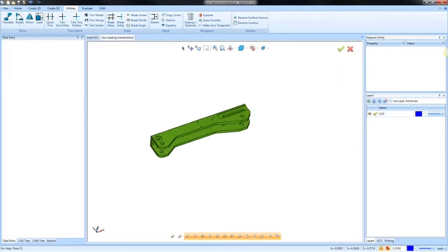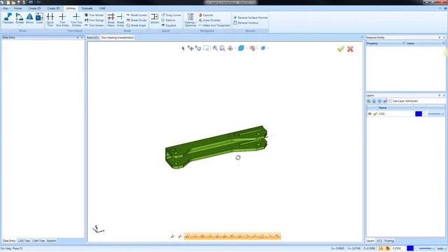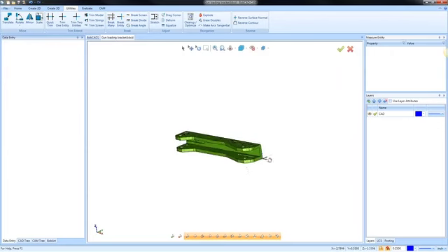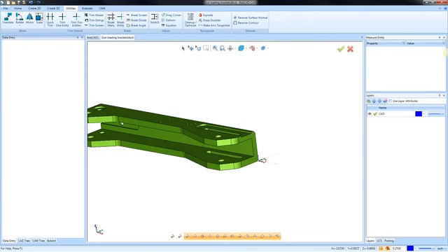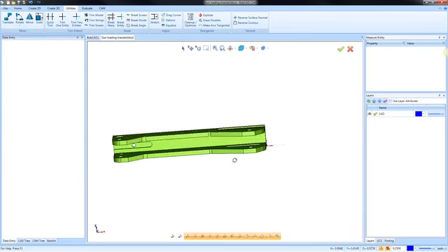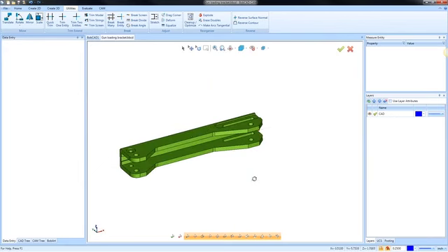When it comes to machining, it really doesn't matter where the part is located, because when you run the stock wizard, you align the stock to the part, so it doesn't matter so much. But again, just to make it easier to edit, a lot of times you may want the top of the part to be at the top of world 0. John says you can define a UCS, a user coordinate system, anywhere. And he's exactly true. So it doesn't really matter, but it can be helpful when you're editing geometry and things like that.